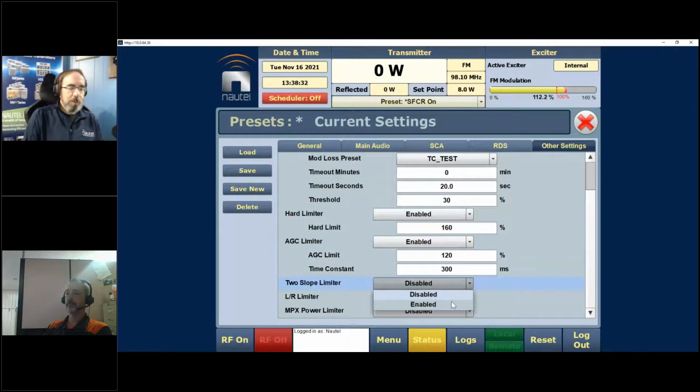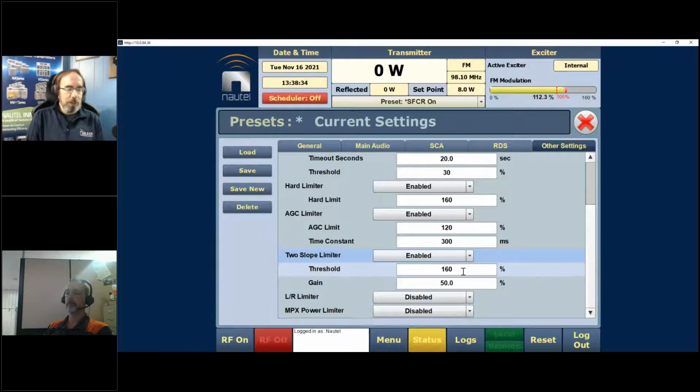The AGC limiter is a fast attack variable release, and you can see the time constant. If you hit that hard, and I've hit it with 160% modulation before, it will pump like a son of a gun. These are not meant to replace proper gain control. They're there just to keep you legal in an if-all-else-fails situation. If you're using the limiters to actually limit the modulation, you're going to get distortion. There is no doubt.